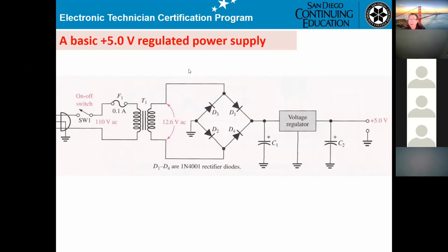So what you need to do, remember, you never care about the wiring. Okay? This wire here, don't care. The thing is basically the board they already built. The wire is under a layer inside the board, so it cannot be broken. The only thing that normally happens is a diode not working, a transformer not working, or something in this circuitry not working. Okay? That's what you need to change.